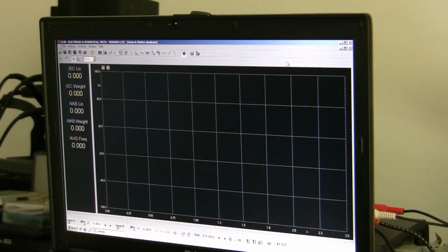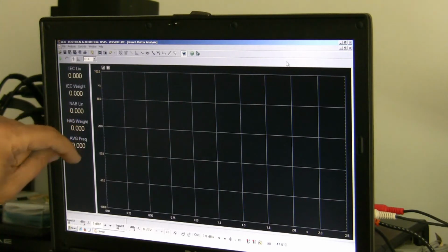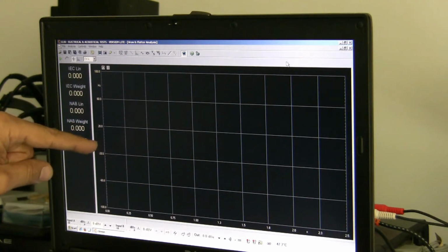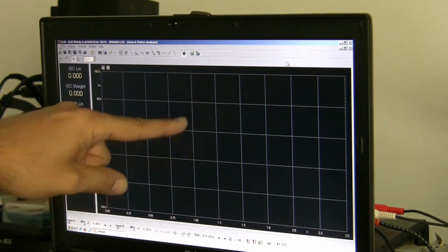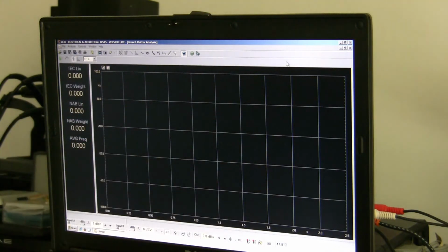Clio will compare the output, which is a fixed sinusoidal tone, and give us the delta of what is being picked up as compared to the reference signal, and it will start plotting it like we in fact see on an oscilloscope screen.